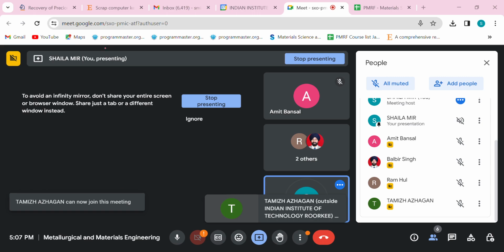Obviously ultrasonic test is a test which is subsurface, so you have to use ultrasonic test also. And then liquid penetration test will not be true because you have to have some surface open for pouring your liquid or your dye into the material, so that should be a surface crack. So liquid penetration and visual inspection are more for surface crack analysis, while magnetic and ultrasonic can go to some subsurface crack analysis also.